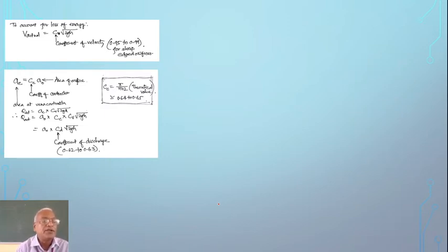So actual discharge will be the cross-sectional area of the flow multiplied by the actual velocity of the flow, Cv root 2 gh. So A naught into root 2 gh multiplied by Cc into Cv. This Cc into Cv is replaced by Cd, which is known as the coefficient of discharge.